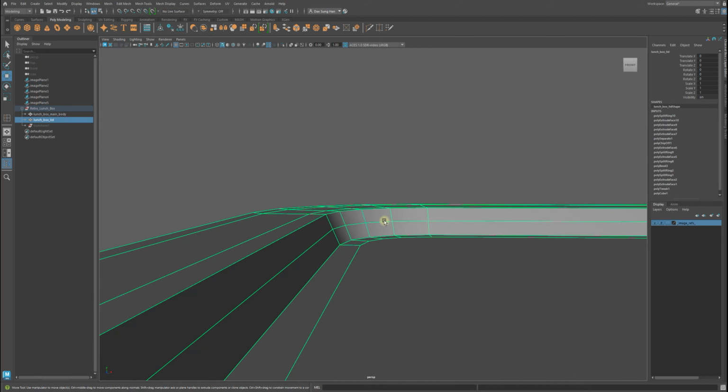So for example, just to clarify better, right? Here, I can select this poly split ring. This basically means that this is the edge loop that I did, and the 10 means I did a total of 10 edge loops. And this here is poly extrude face 10, which tells me there were 9 previous extrusions that I did before. Anyhow, I'm going to select the poly split ring and the weight, right?